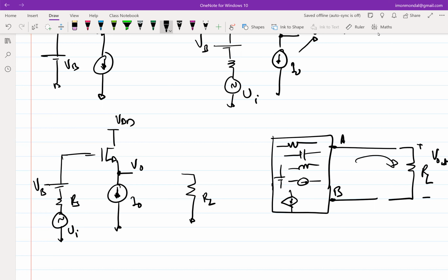So looking inside this box, to a layman, it will definitely seem like there is a source inside. Since there is a source inside, I am extracting power out of it. I am getting some voltage at RL. So all we know is whenever we say there's a source inside, it either is a voltage source or a current source or a mix of both. Okay. So under the condition that I have shown right now, how would you conclude approximately what does this source look like? Does it approximate a voltage source or does it approximate a current source?